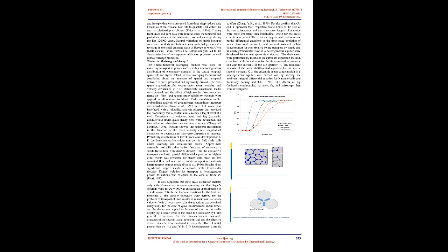General equations for the first two moments of the particle trajectory were derived for the problem of transport of inert solutes in random non-stationary velocity fields. It was shown that the equations can be solved analytically for the case of quasi-unidirectional mean flows, and the theory was applied to the case of transport in media displaying a linear trend in the mean log conductivity.